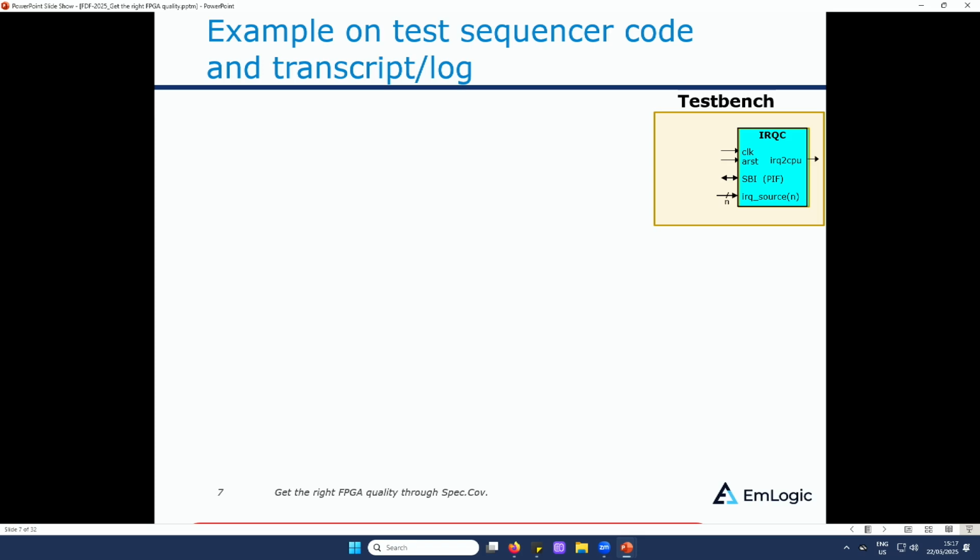Then we make a test bench around that. And of course, the first thing we need in any such test bench is to have a clock generator. And in UVVM, that's dead simple. In the utility library, you have lots of procedures for generating clocks. And the nice thing about procedures in VHDL is that if you put them into the architecture rather than into the process, it works as a so-called concurrent procedure.